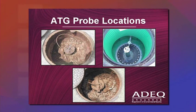So this is what the ATG probes look like. They sit right up on top of the tank and they go directly into the tank. This is the only release detection method that has something that goes directly into the tank, the automatic tank gauge system.